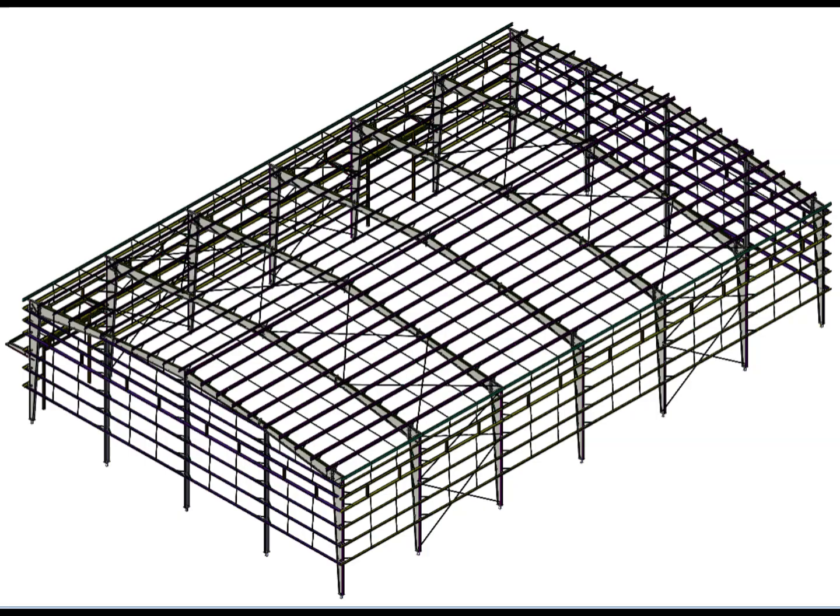Never study an individual drawing in isolation. Connect the information between drawings. The elevation tells you where the member is located. The framing view helps you understand its arrangement. The connection detail shows how it is attached. And the 3D model helps you understand how everything comes together spatially.